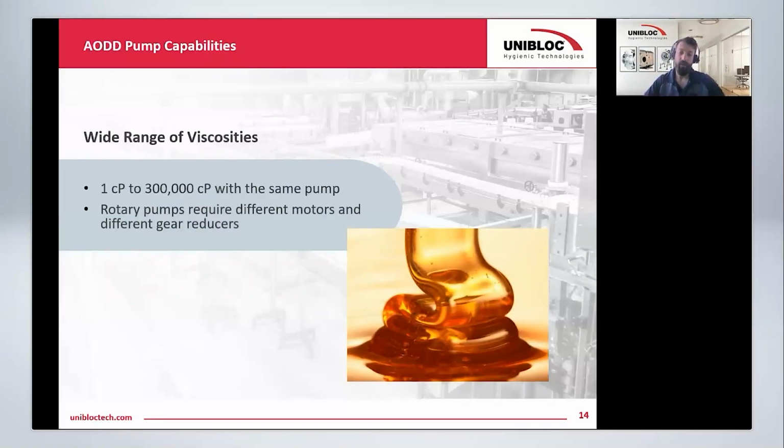That's not an issue for AODDs. They will easily pump something as thin as water or something as thick as tomato paste with the same pump, and there's no need to change anything about it to make it fit those applications. An example of this is we had a global personal care manufacturer that needed to pump their full range of hygienic products to fill depositors.